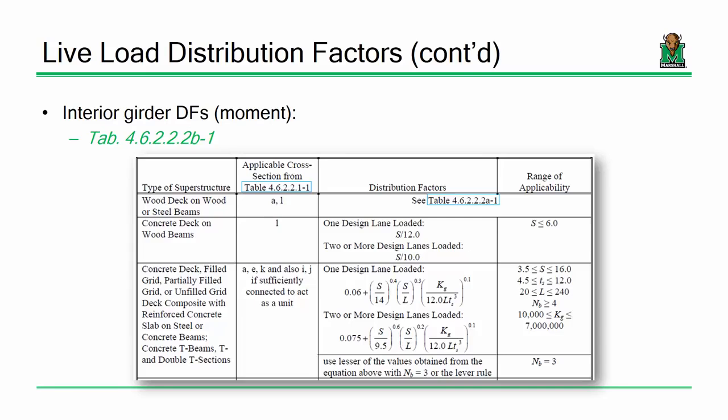And that's by and large a pretty good range for most typical bridge designs. Okay? Now if you've got a two-span bridge where each span is 90 feet, well that still fits because each span's 90. Okay? A girder spacing anywhere from 3.5 feet to 16 feet. That is a heck of a range. A slab thickness anywhere from 4.5 inches to 12 inches. Pretty good. Okay? Make sense? Any bridge where you have a number of beams greater than 4, which is what we're going to do anyways in America. So no big deal.